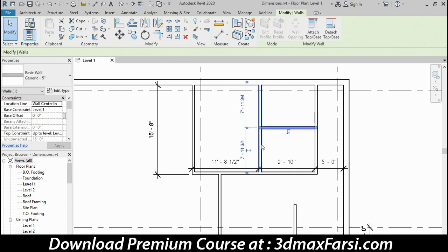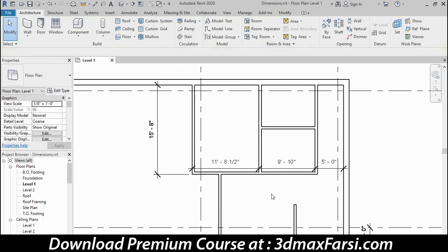And by doing it that way, I don't have to figure out what the numerical value is and do the math. I can simply say, let's move this wall to the midpoint of this other wall, and now I know that it's bisecting that space into 2 equal spaces. So it's just another way to achieve a similar effect. Now let's do one more move command.